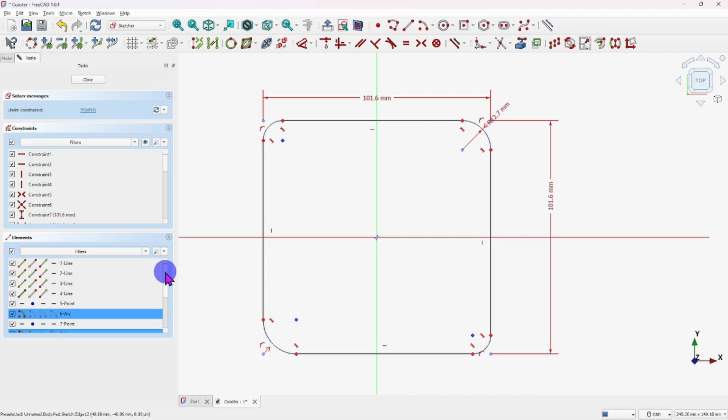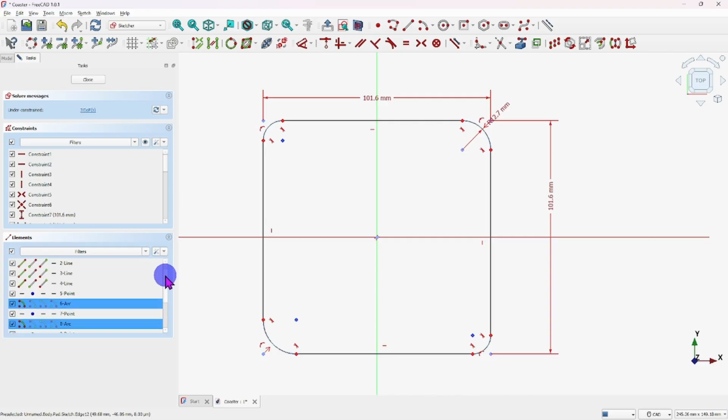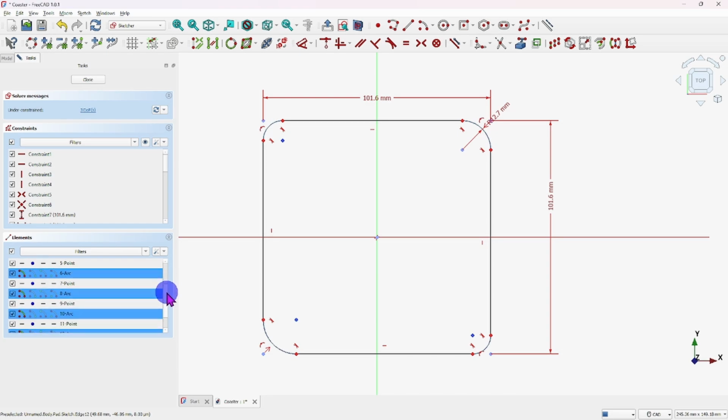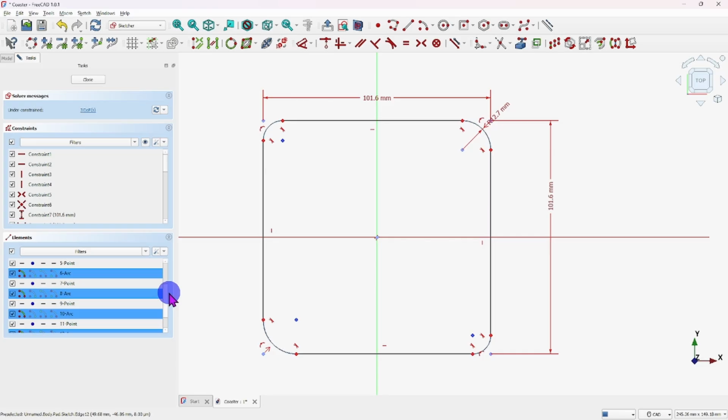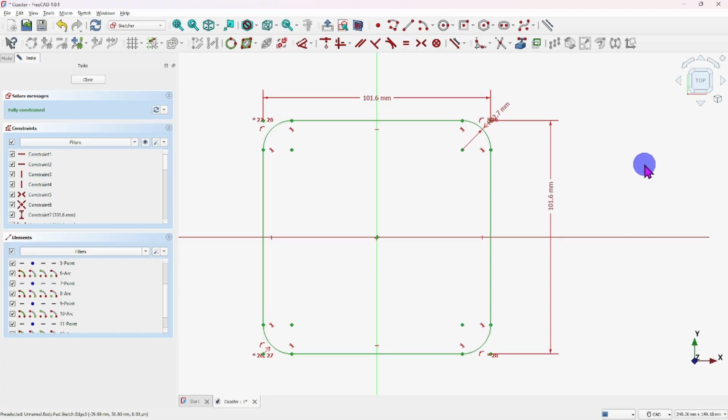I'm going to take a minute here to show you that as you're selecting, over here under the elements, it shows you what you have selected, because sometimes I'm selecting these and they're not staying highlighted, at least in the view. But over here I can see where they are, all 4 selected. Okay, so with all 4 selected, I'm just going to simply hit the equal sign. And there, now all radiuses are set to that 1.